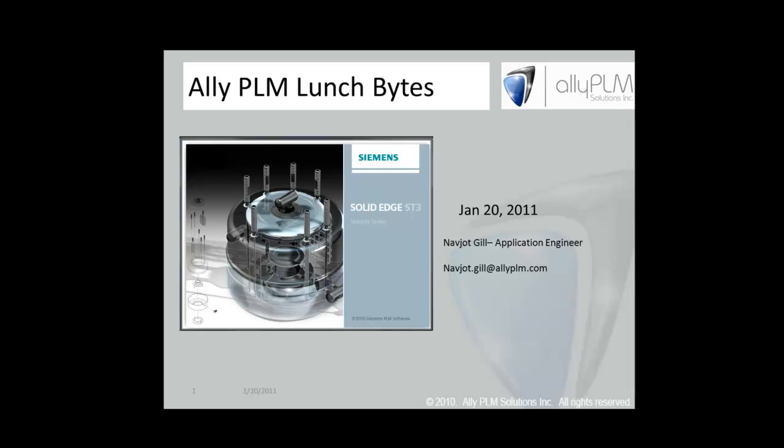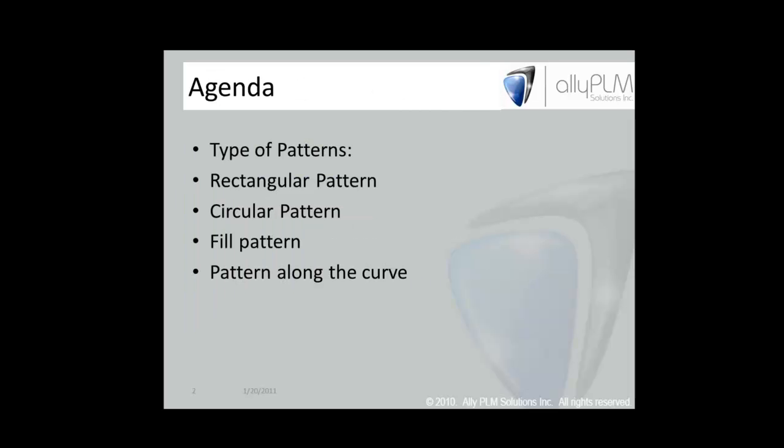Today's topic is patterns. As far as the agenda is concerned, we'll be covering different types of patterns. For example, rectangular pattern, circular pattern, fill pattern, pattern along the curves, and also we'll be defining some subtypes of fill patterns such as radial pattern, staggered pattern, and rectangular pattern.